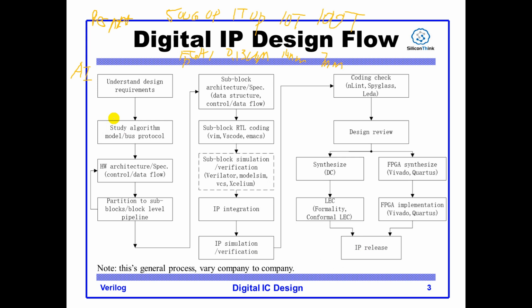Then for the next step, you have to go deep in the algorithm. At this step, you may need to build an algorithm model for your function. Maybe you will use C language, or MATLAB, or Python to build the model. This model will be used at the simulation stage. And if the algorithm is rather complex, you may have to read some papers at this stage.